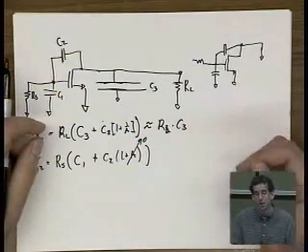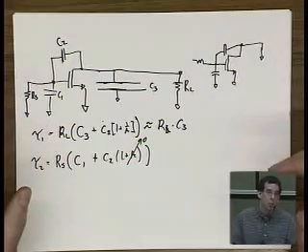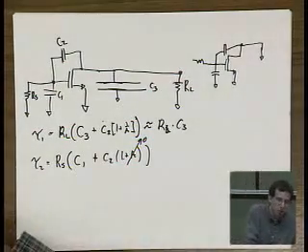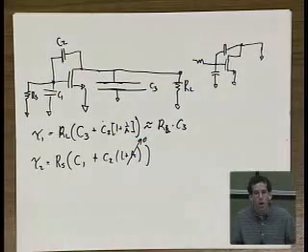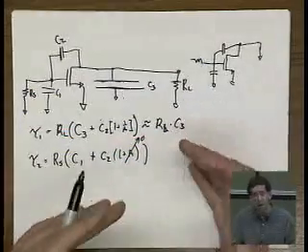And zero value time constant analysis, when you're talking about open loop amplifiers, where you basically sum up all the small poles together to get one big pole, is really useful when all those capacitors are intermediate. And Professor Broderson talked about it briefly. In my class, I spent around three weeks on zero value time constant analysis.